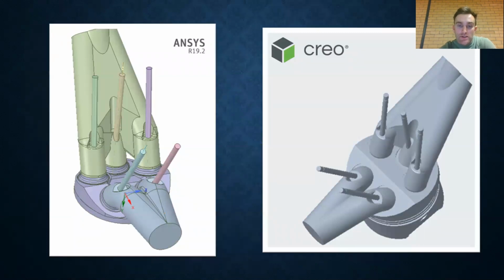I then used Ansys SpaceClaim to further refine the models and prepare them for IC Engine. I found that Ansys SpaceClaim was better suited to making changes to my geometry than Design Modeler or Creo, as it allowed for more complex modifications with ease of use. I then just opened my geometry in Design Modeler to prepare it for decomposition.